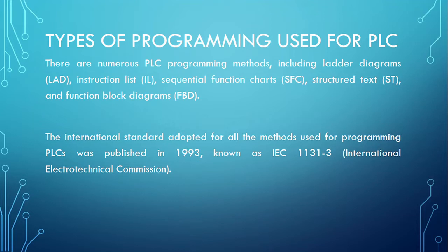And these programming methods are: number one, the ladder diagram, the instruction list, the sequential flow chart, the sequential function chart, then the structured text and the function block diagram. So these are the methods used for programming a PLC. All of the methods are appropriate. However, you can have a preference based on probably your understanding of such programming methods.